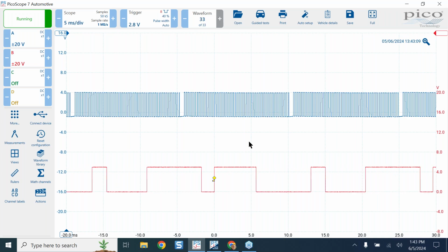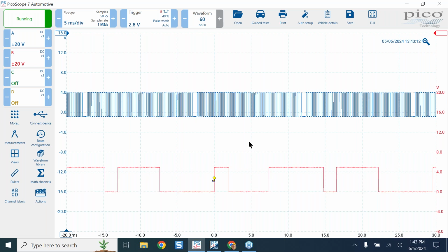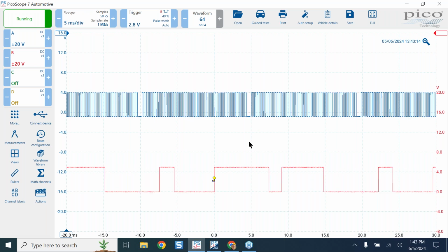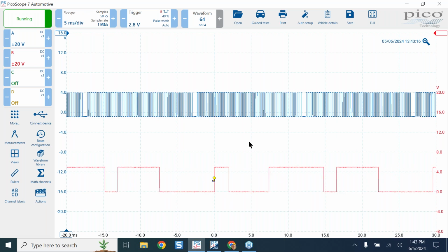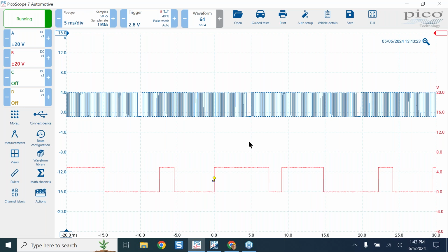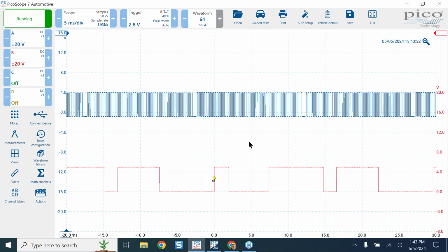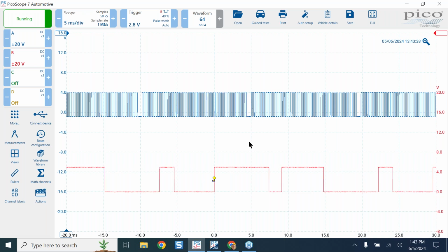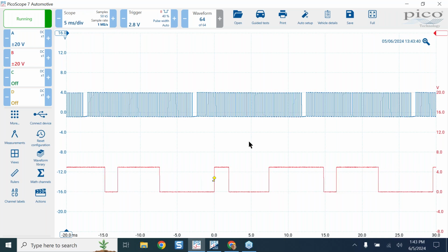Just as we're getting some questions and comments in, some have created the best practice of triggering off of the ignition primary one, and even having a low amp current probe as well. You could do that. Yes, you can certainly do that as well. I don't have that in the simulator, so that's why I'm using cam and crank, to be perfectly honest with you.